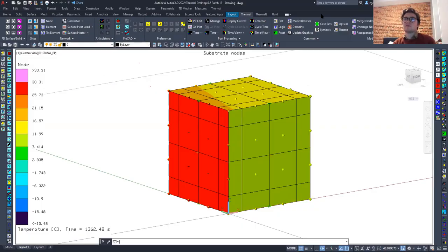I think the reason is because there were bolts, but that's a dumb thing to do, because there are bolts, yes, but you're also pressed against the surface. So you definitely want to use surface to surface. I would not use single node to node contacts for that. Yeah, that was a dumb idea. Sounds like something we would have done. Don't do that. Be smarter than that.